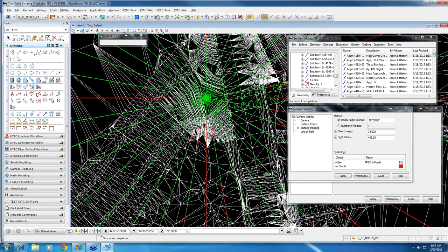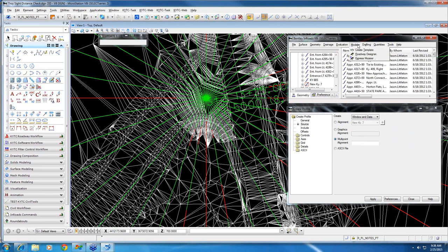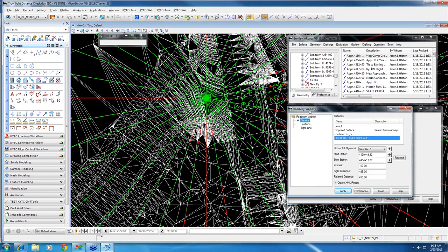And then another thing that somebody brought to my attention, they've been having some sight distance issues in their district with situations where at an intersection it technically meets the sight distance, like you can see the prescribed distance ahead an object that's 2 feet tall, but you can't actually see the roadway, and so it kind of was freaking drivers out. So one thing you could do to check for that, not saying you need to or have to design for that condition, but it might be good information to have, is if in the roadway